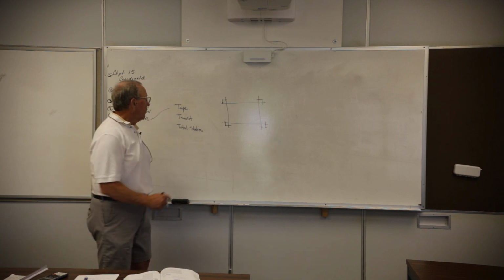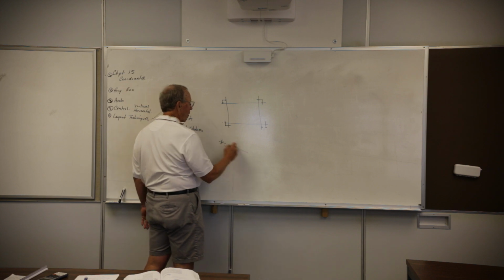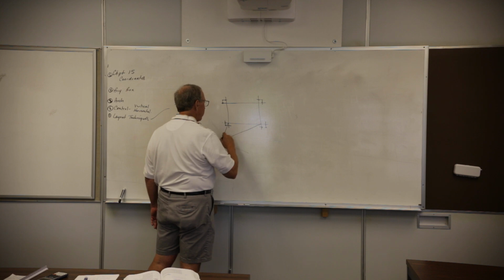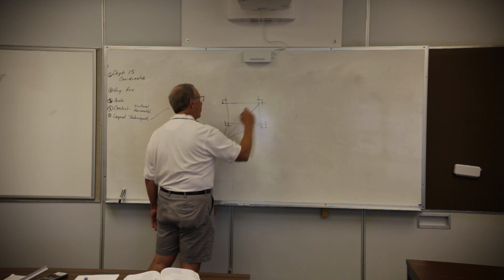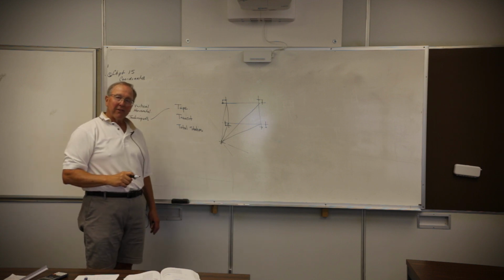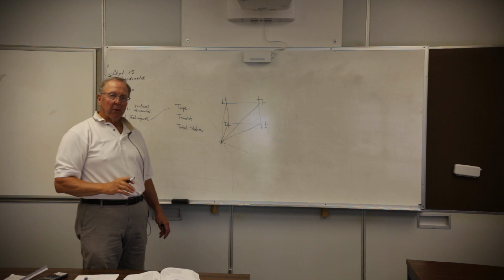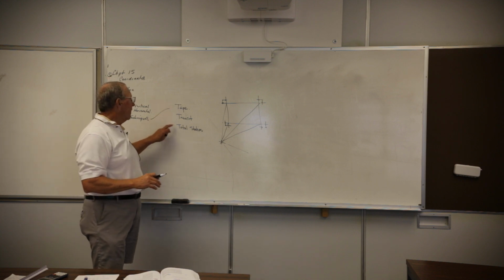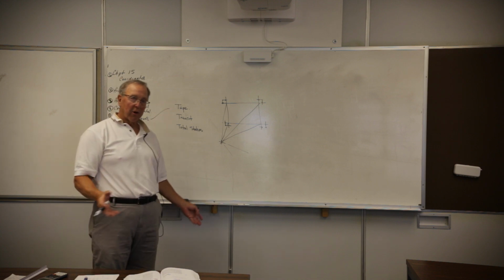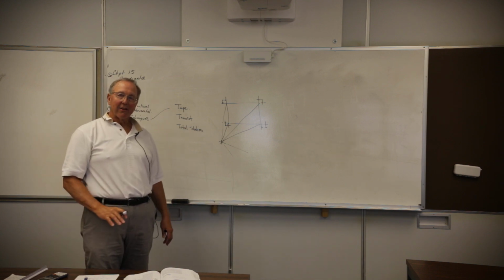Another thing we could do is set up a total station, index it to our control, and then have this total station turn angles and measure distances and lay out corners. So you've got a very wide range of capability between these three, integrating those together, using one all by itself, using two at a time in order to lay stuff out.